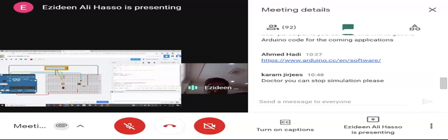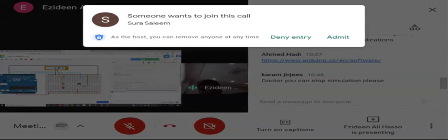Okay. So now, if I start again, and if I press, did you see what happened? I want you to look at the serial monitor. Now it's sending ones because I'm pressing, so I'm asking to turn the light on, okay? The switch is giving 1 to the board. It's sending 1 to the Arduino to pin number 2, okay?